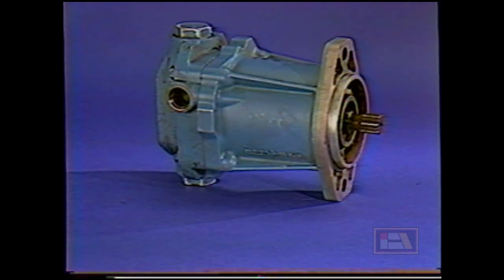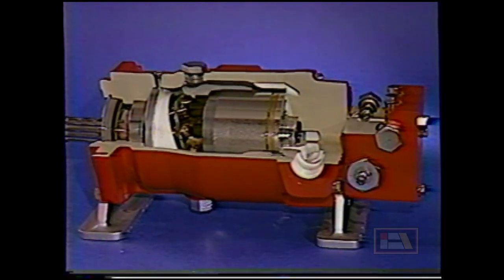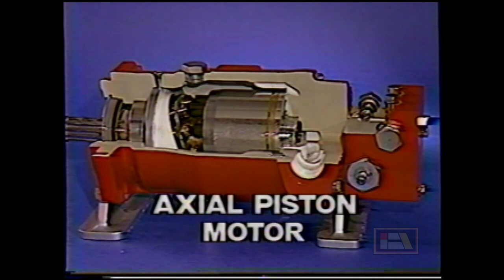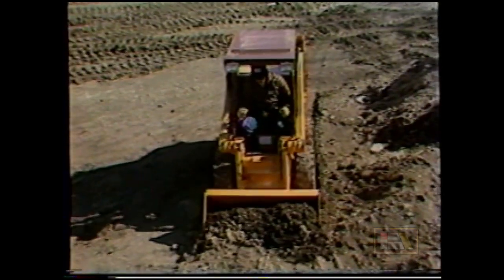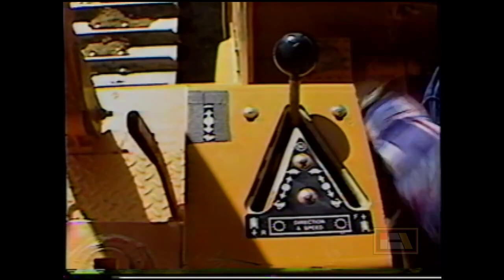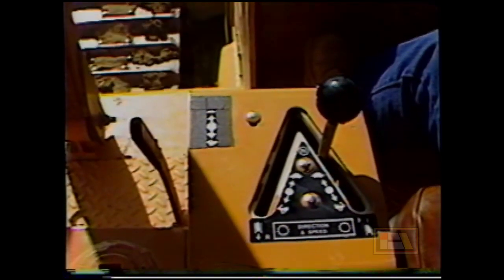The motor in the hydrostatic system can also come in a variety of shapes and sizes. The type most commonly used is the axial piston motor. The relationship between the hydrostatic pump and hydrostatic motor is simply to convert the mechanical energy from the engine into fluid energy, then to convert that fluid energy back to mechanical energy. To control a hydrostatic system requires anything from a simple hand lever to a sophisticated pilot-operated servo control system. The control system lets us determine the speed and direction of the output.